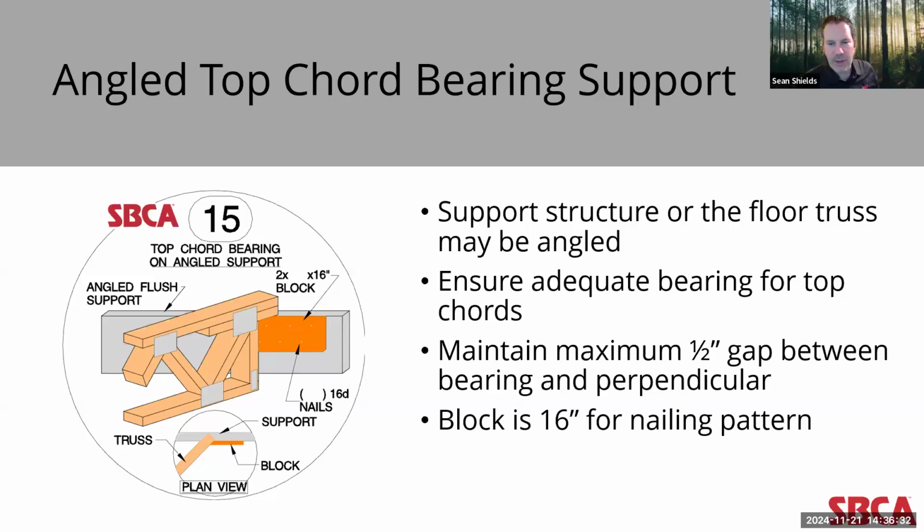Now in this application, it calls out for a 16-inch minimum length of that blocking to provide enough nailing surface for the required number of nails.